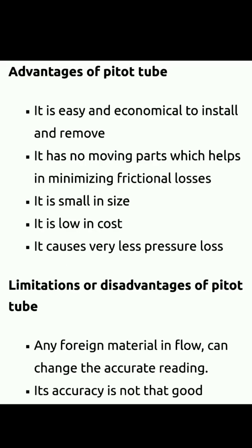Now, the advantages of the pitot tube. It is easy and economical to install and remove. We can easily remove it and easily reinstall it. It is very simple. It has no moving parts, so we do not need to worry about wear and tear and other friction losses. It is small in size. It is a very small glass tube, so the size is very small.